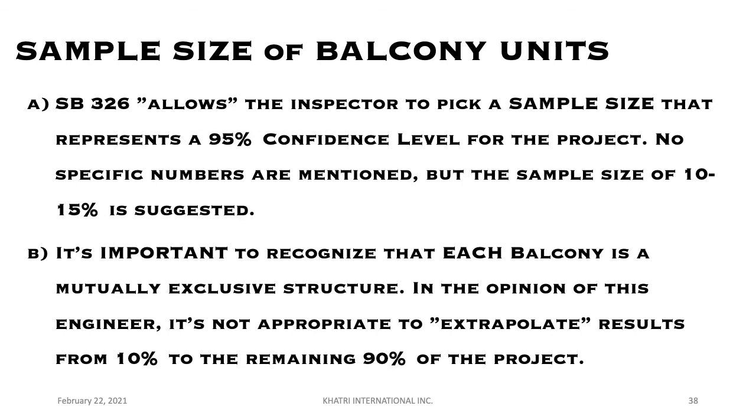Another thing I wanted to talk with you about is sample size. So the Senate Bill 326 allows, and I put that in quotes, the inspector, which is me or someone else, which would be a licensed engineer or a licensed architect as per SB 326. For HOAs, contractors are not permitted to be doing the inspections. It has to be a licensed design professional. So they allow us to pick a sample size that represents a 95% confidence level for the project. No specific numbers are mentioned, but a sample size of 10 or 15% is suggested.